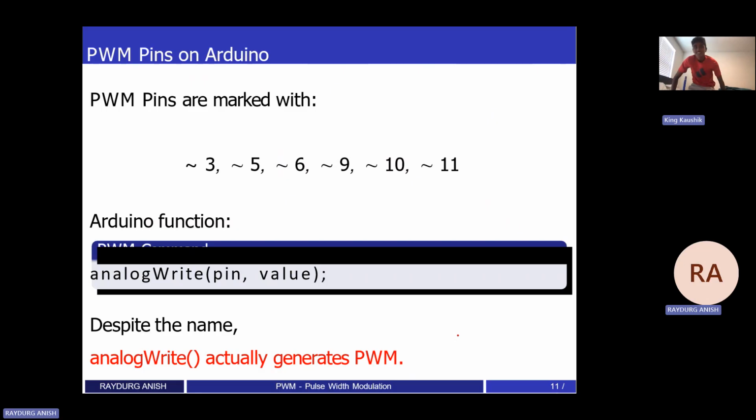Okay, now get the Arduino board and look for these marks. Remember, you saw it in the video: the curly things. When you see these curly things, it means that the corresponding pin is compatible with PWM. Those pins can produce the PWM signal. It shows it on the Arduino itself: digital, PWM, and then the curly thing.